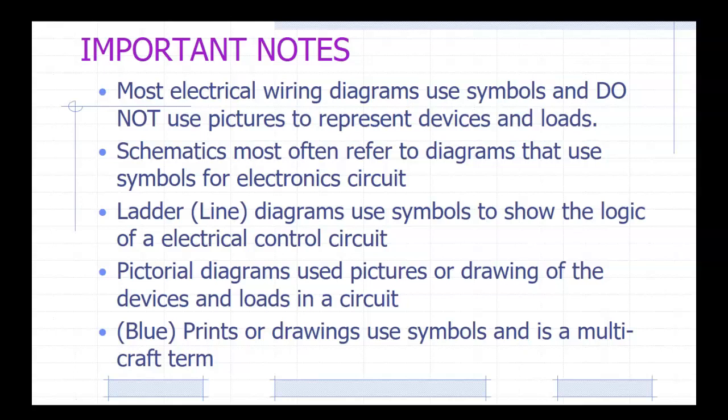They often refer to diagrams that use symbols for electrical, schematics most often refer to diagrams that use symbols for electronic circuits. Like I said, schematics are very commonly used. Ladder diagrams show the logic of a circuit, and we've already kind of talked about that. We'll talk about it a bit more as we get on into this chapter. Pictorial diagrams use pictures of the devices and loads in a circuit. And blueprints or drawings use symbols and is a multi-craft term. Blueprint is probably one of the most common terms.